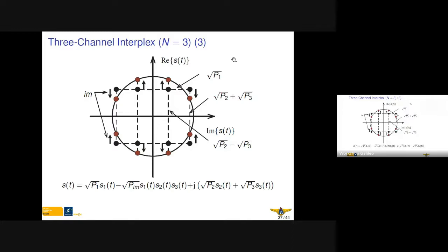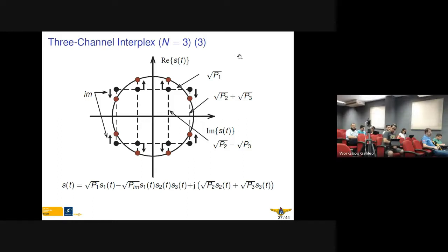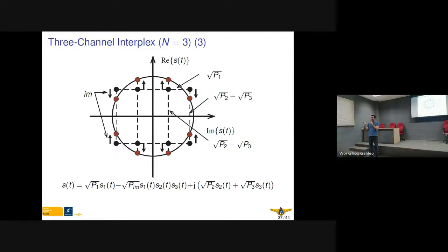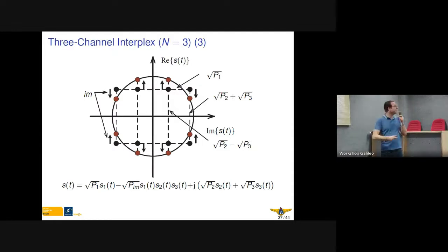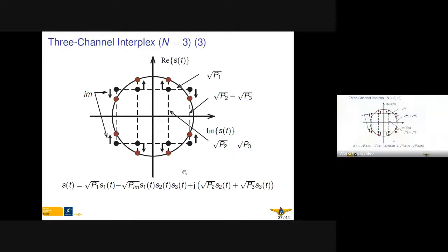And when we add the intermodulation, we then transmit no information, right? We don't lose information. We add another signal that is built from the other signals, a multiplication of all the other signals, and we don't lose information because all these signals in the receiver are separated by correlation.